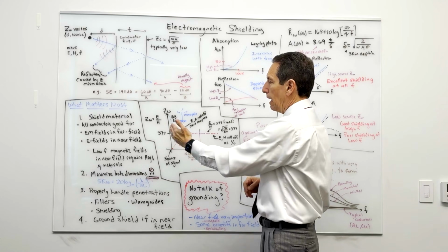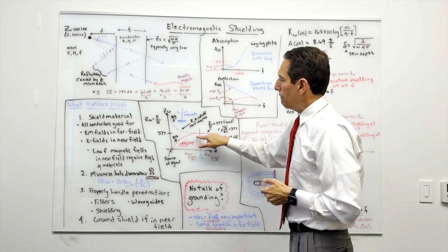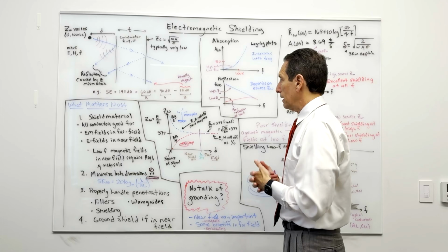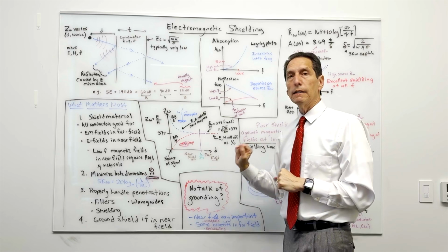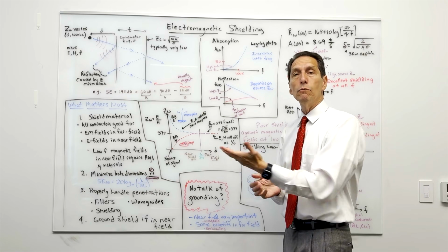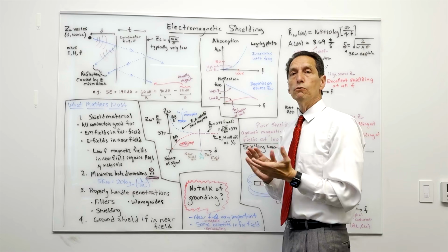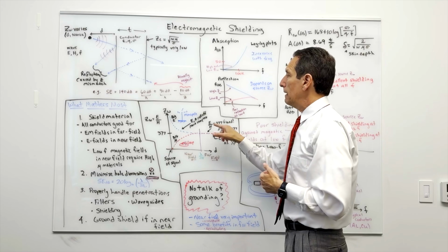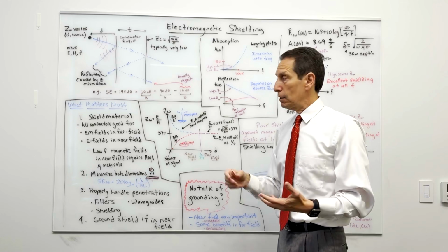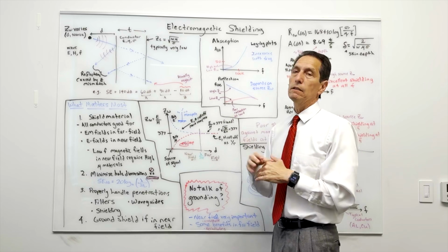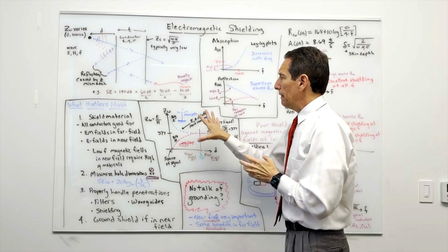Now, what's interesting is as you move further away from the antenna, they come together. All right, they come together, and eventually they come to the same value. All right, and in free space, that's a fixed number. It's 377. So the electric field to magnetic field ratio is 377 when you get far enough away from either of these two types of antennas, either extreme, which is really fascinating. All right, so it means if you get far enough away, it doesn't matter what kind of antenna you had. But when you're up close to the antenna, it makes a big difference in terms of this wave impedance. All right, and the wave impedance is going to be very important in determining how this shielding effectiveness works out. All right, so that's what this chart is saying here.